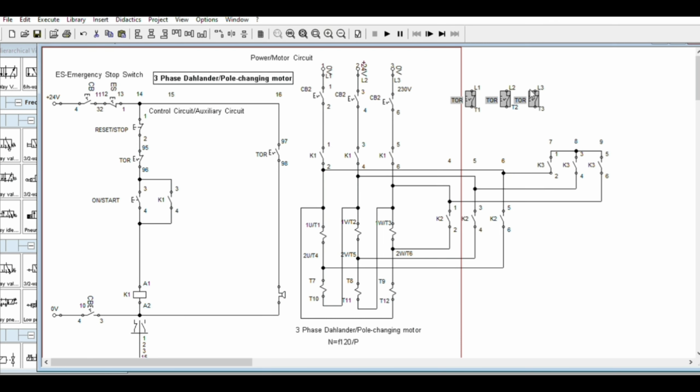So if we need the line contactor, we have to add that for safety. Let's say, for example, we want this one as the line contactor. The controlling or line magnetic contactor, sometimes called isolating contactor. You may add or you may not want this one for additional cost, but usually this is added for additional safety.